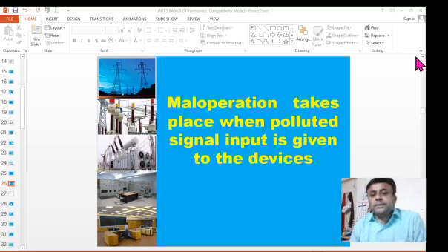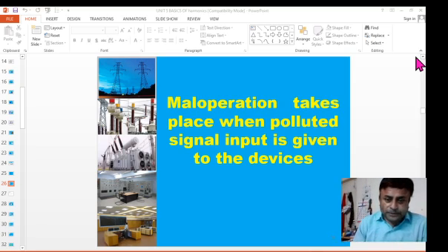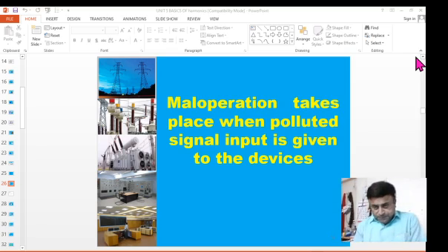So far we have had an introduction about what harmonics are. We have seen that harmonics are integer multiples of the fundamental frequency. Ideally the wave shape must have a single component, that is the first harmonic. However, because of nonlinear load there is harmonic distortion in the wave and it becomes non-sinusoidal.